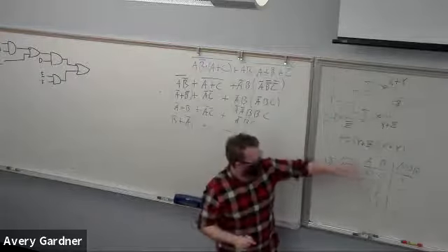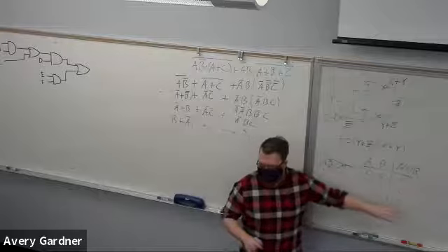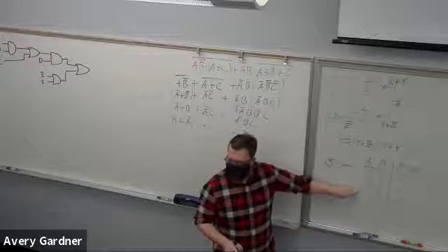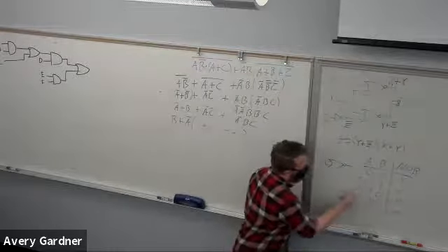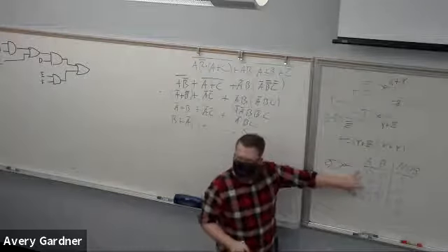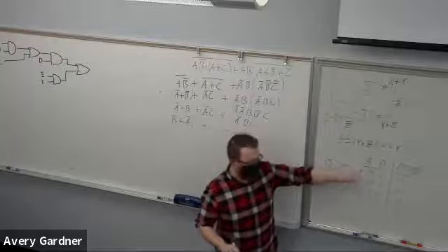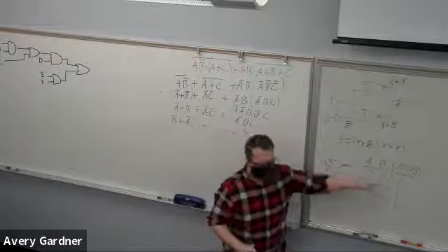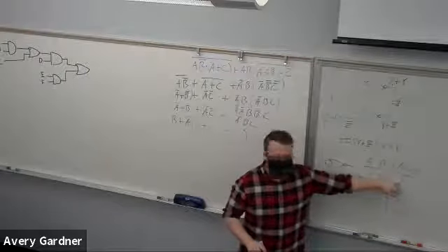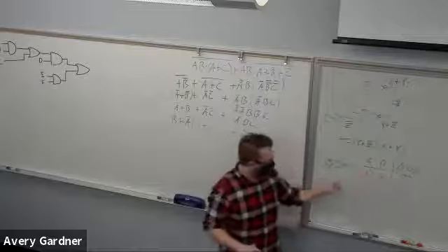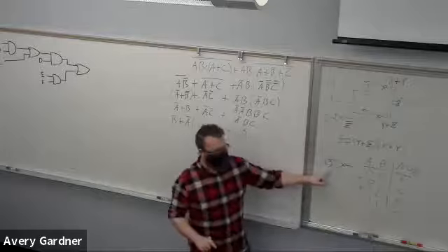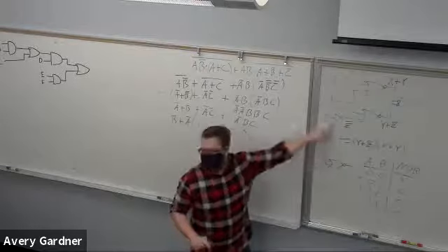Yeah. So I want to start off with the NOR gate so that we can follow through. But you're right, because this can't happen. Those are impossible if A equals B. So the only rows that matter are row 0 and row 3, right? Because those are the rows where A and B are equal. So if the input is 0, it's 1, and if the input is 1, it's 0. That configuration for a NOR gate is equivalent to an inverter.